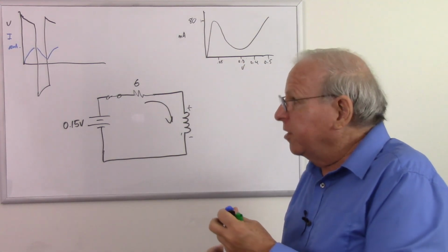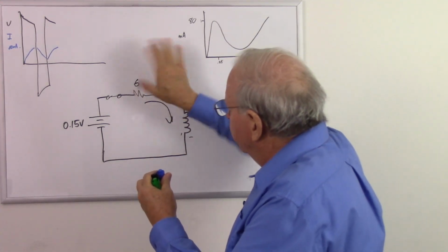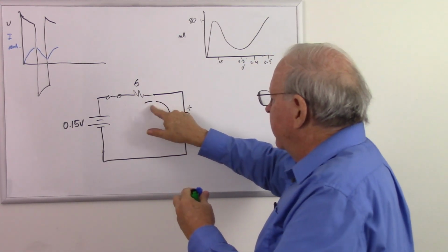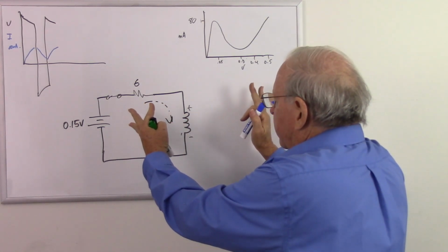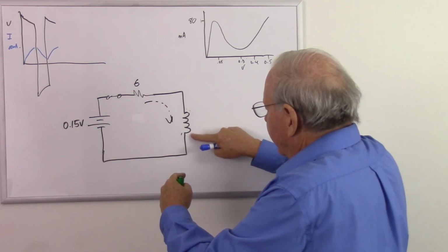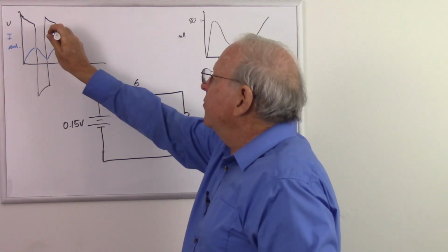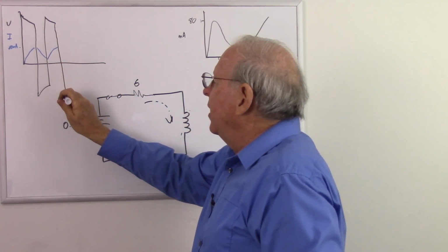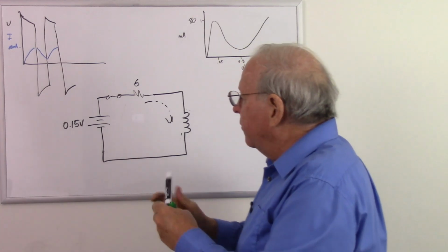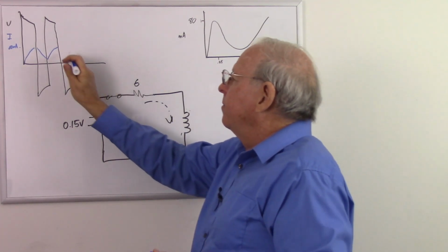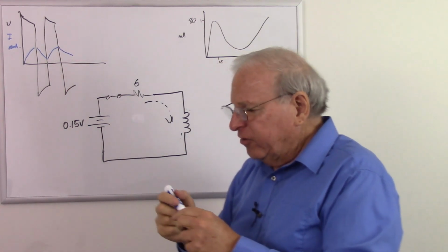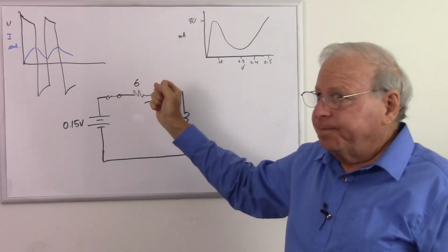I'll explain that in a little more detail in a minute. It's going to switch to a high impedance again. That's going to slow down the current. Magnetic field is going to start to collapse. Again, that's going to change polarity, and everything is going to cycle over again. So in a slightly oversimplified view, that tunnel diode simply acts like a resistance that keeps changing.